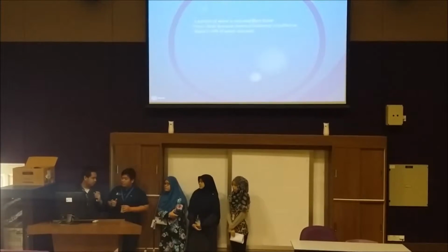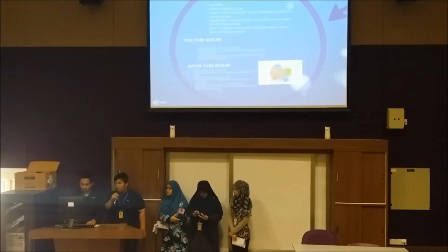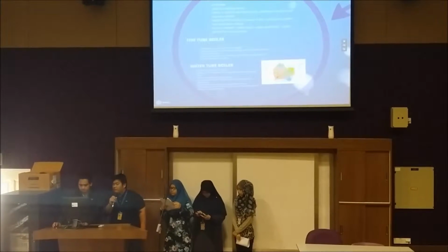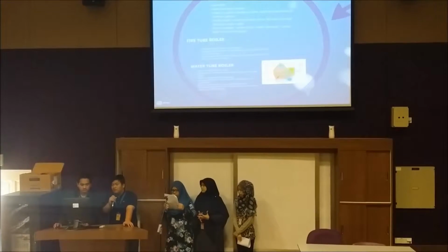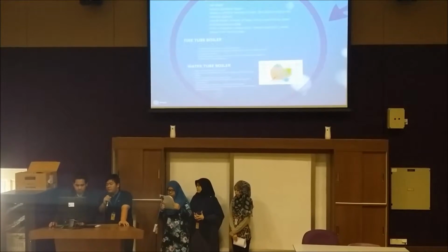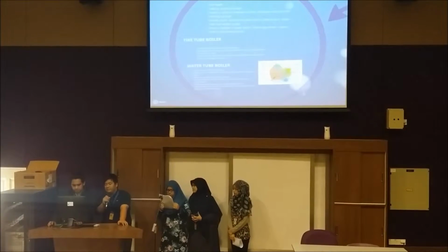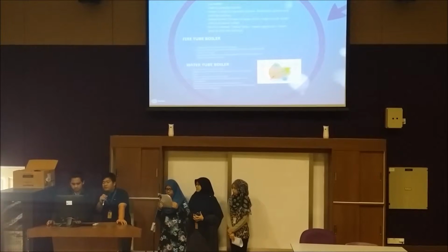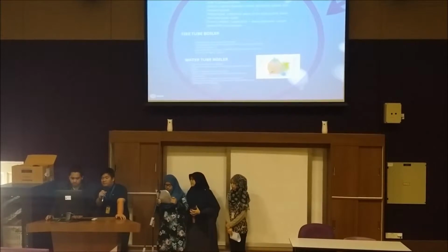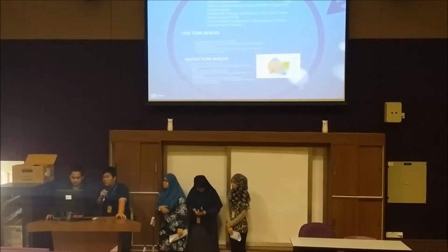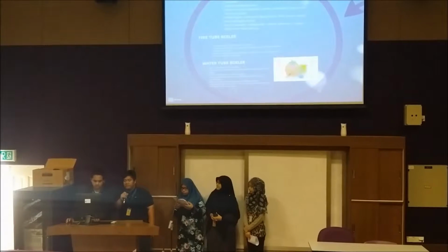Next I will pass to Ifan. I will present the boiler application and operation. First, the boiler uses water. The water is used to produce steam, and the steam is used to operate the turbine, distillation system, and reaction system. The simple boiler consists of a water drum, heat source, water inlet, and steam outlet. The drum is heated, then the water boils. After that, the steam generates, and finally the steam goes to the next process.